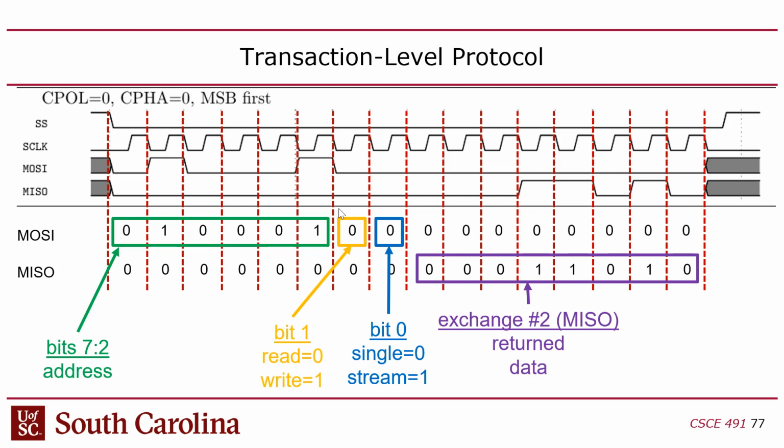So it's a length field, a whole 8-bit length field, at which point the subsequent exchanges will be either the read or write sequence. In that case, the address is the starting address: you give it a starting address, a length of the transaction, and then the transaction bytes. That's a little different than what we showed in the last lecture because these transaction protocols are arbitrary.